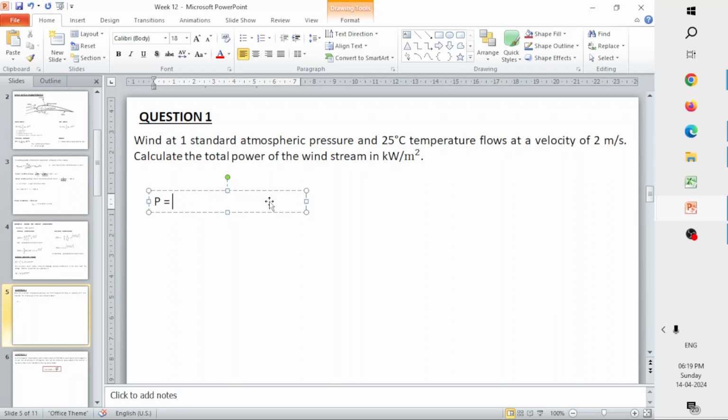Yeah, you can take that and do it, but like last time, if you remember, we discussed that rho is nothing but Pm by RT. Since here it's given as 25 degrees Celsius, it will be easier. But if, let's say, the temperature was 35 or 45 degrees Celsius, then you are supposed to use Pm by RT and get the value. So your P is nothing but the pressure. Yeah, so 1 atmospheric pressure is nothing but 10 power 5 pascals.